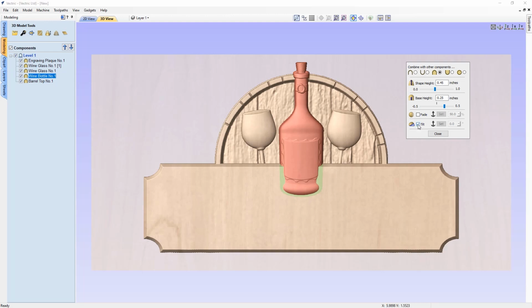So if I select the tilt option, I can then go ahead and set my 2 anchor points. I'm going to set my first anchor point here, which is going to tilt from here, or this is going to be the axis of tilt. And I'm going to go down this way, and this will actually be the high point once I tilt it. Now I can go ahead and put in a degree in here, 1 degree. We're going to press the space bar and you'll see what happens.